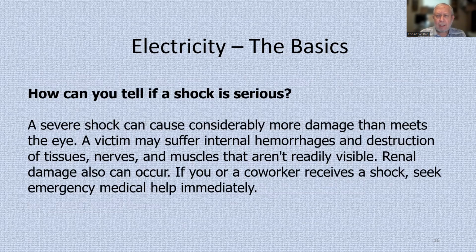How can you tell if a shock is serious? A severe shock can cause considerably more damage than meets the eye. The victim may suffer internal hemorrhages and destruction of tissues, nerves, and muscles that aren't readily visible. Renal damage also can occur. Renal means your kidneys. If you or a coworker receives a shock, seek emergency medical help immediately.